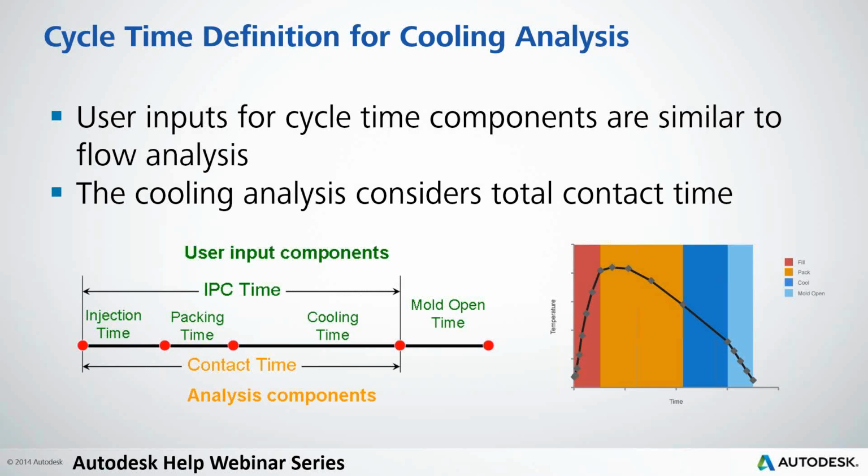As you can see on this small graph, the temperature is also not constant through the different steps. In the injection time, the cavity surface is getting warmer, and then the temperature just decreases through the packing, cooling, and mold open time. As we will see in another picture, it is also not such a big jump in temperature. We are talking about 15 degrees on the surface of the cavity. The complete cycle depends mainly on the geometry and the volume, but could be about 20 to 30 seconds, or longer, of course.